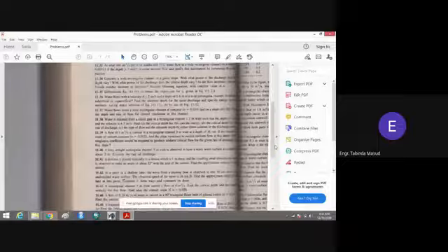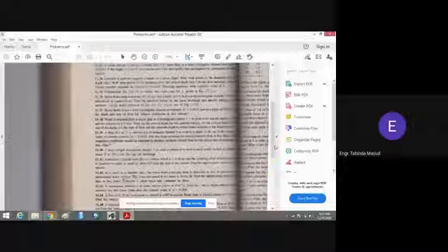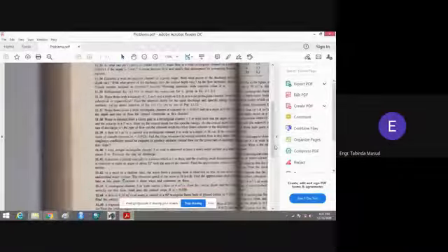It is page number 394, problem number 36. It is written that water flows with a velocity of 1.2 meter per second and a depth of 0.6 meter in a wide rectangular channel. Is the flow subcritical or supercritical?